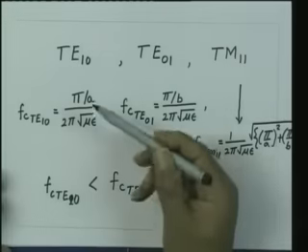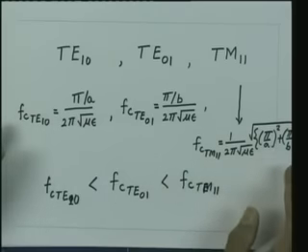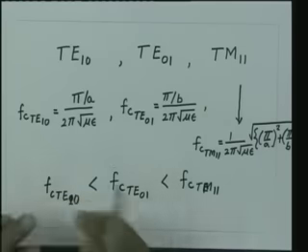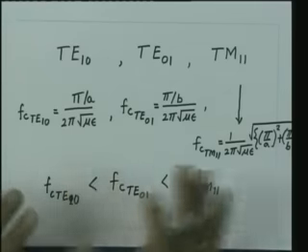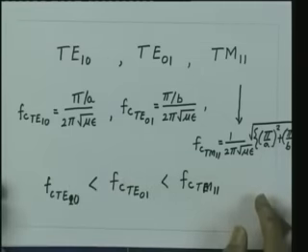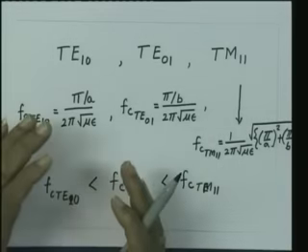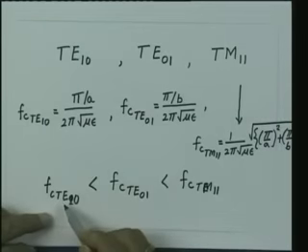And we have seen the mode TE00 or TM00 do not exist. That means this is the lowest frequency which can propagate on the structure. That is the absolute minimum frequency which the structure will support. So, whenever we try to excite a rectangular waveguide, the possibility of exciting this mode is the highest, because if at all the energy is going to propagate, it will be propagating at least at this frequency.